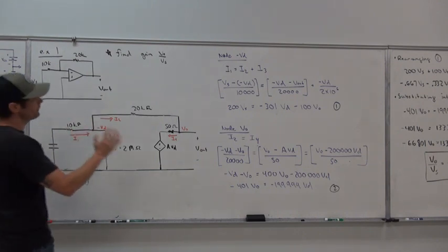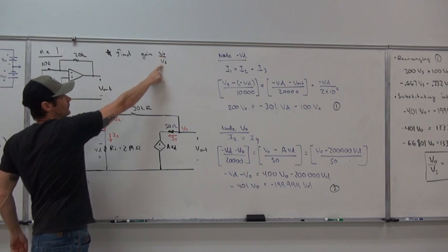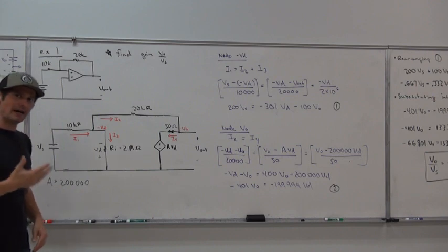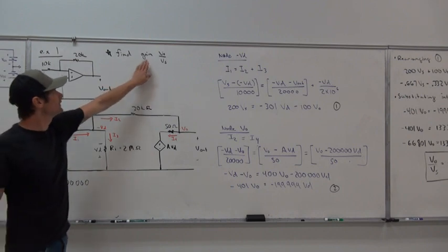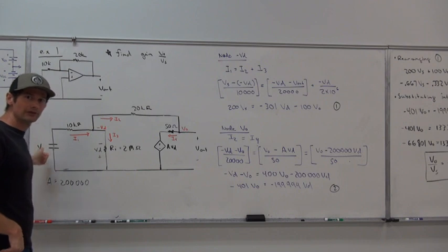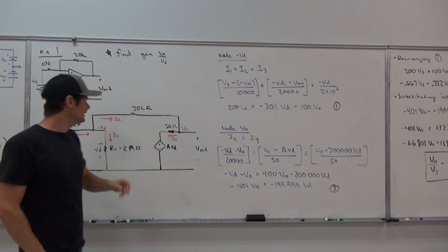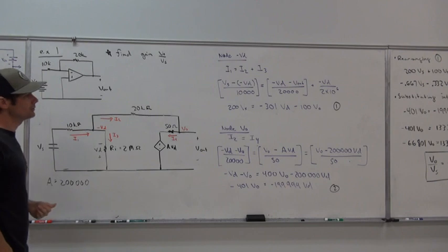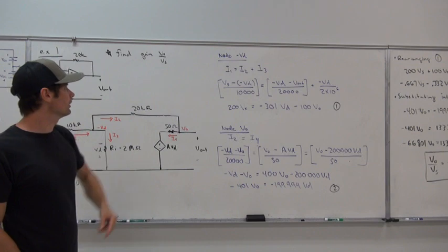And so here we want to calculate this closed loop gain of the output voltage to our input here. And Vs, it doesn't actually matter what this value is, because what we really concern ourselves with is the gain itself. So the ratio at which, if we put an input voltage Vs here, what will we actually produce on the output? Now we're going into the negative terminal here, so whatever voltage we get out here, we should get a negative or inverted polarity at the other terminal of V naught.